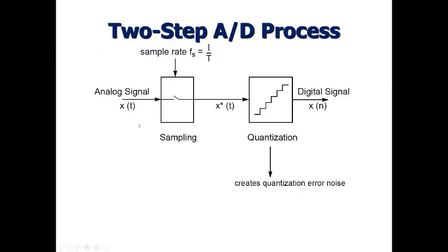First, we have our sampling process, which is usually carried out by the sample and hold circuit. We recognize that part of what's going to go on in that conversion of voltage level to digital output is actually a quantization operation. It's going to be some rounding involved. We're going to turn a continuously varying voltage into one that has certain staircase, discrete levels that we can depict with our finite number of bits in a digital signal.